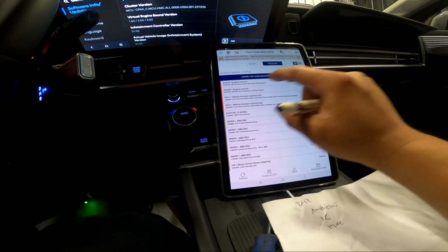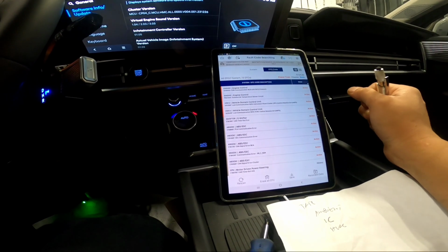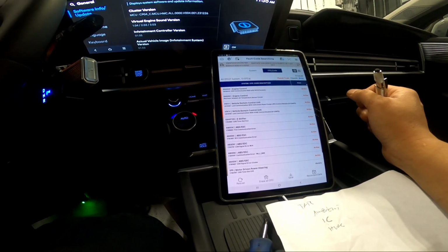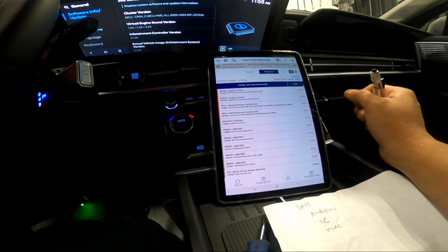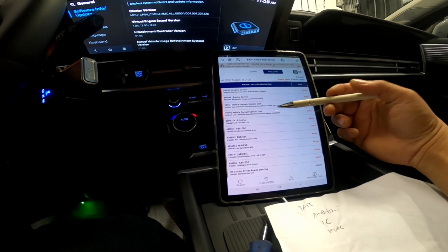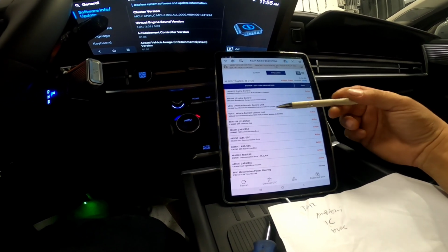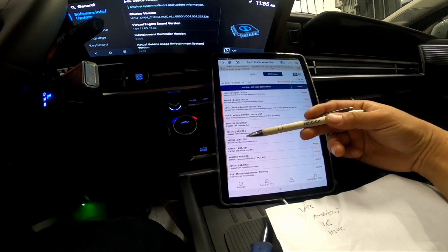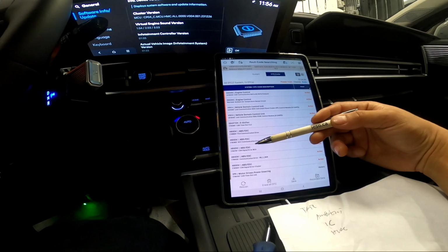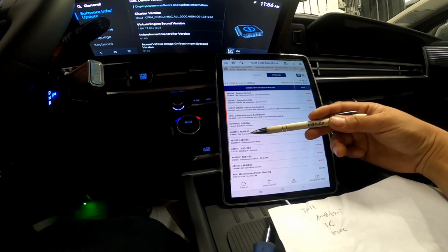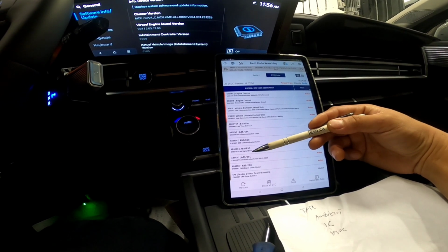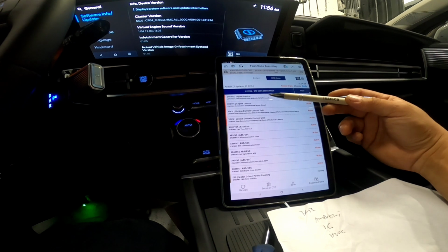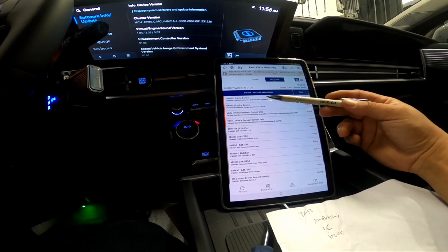So let's see first our ambient temp, what's going on there. I think that's the easiest one to check, and then we're gonna go through, and maybe it's just a communication issue. Maybe there's a common connector here, because the ABS is saying that it can't communicate with the smart cruise control, or there's an error, especially on our FATC.